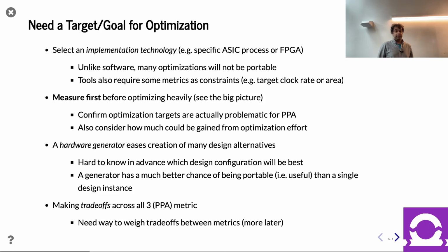So for either technology, when you think about your power consumption, there's your static power and dynamic power. We'll come to this later in the quarter, but I can summarize it right now. Static power, you can reduce by shrinking your design. Dynamic power, you can reduce by changing how many bits toggle. For example, we had that queue optimization where originally we had our FIFO with this massive shift register, and we changed to the MEM where we had things in place, with fewer bits flipping, that would be more power efficient.